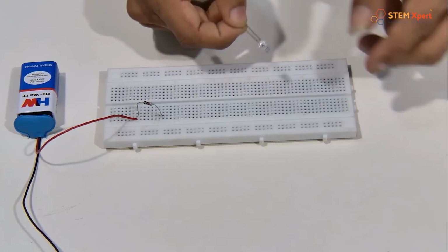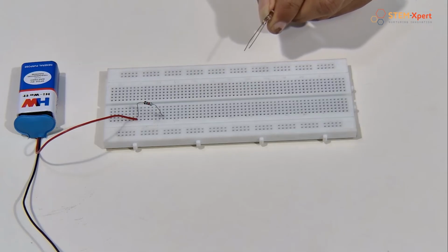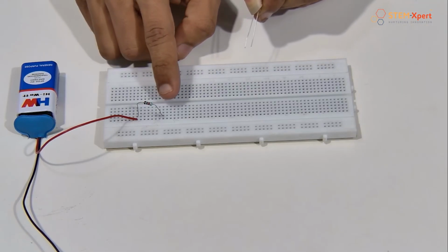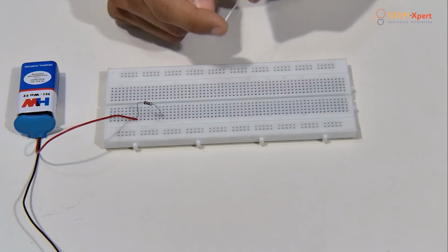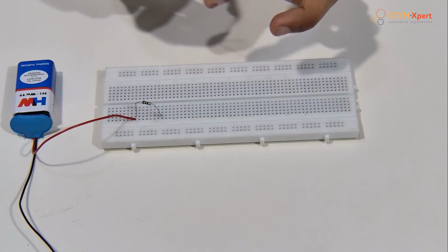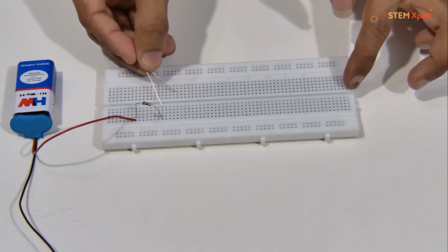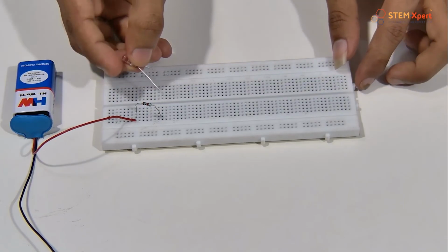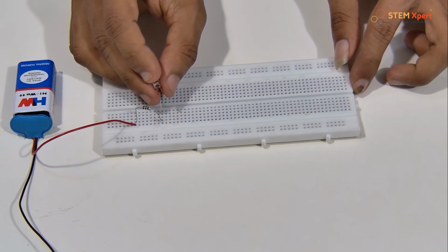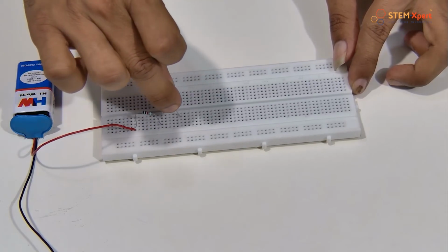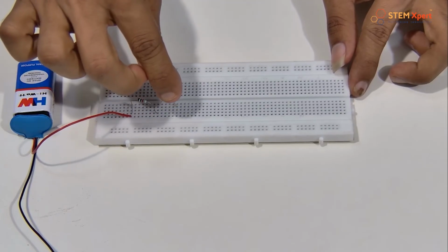You can select a different color of LED from your electronics components kit, no issues with that. So we know that the LED has a positive, the larger one is positive and the smaller one is negative. The thing is that we need to connect the other end of the resistor to the positive of the LED, right? Yes, here I am going to connect the positive to the other terminal of the resistor. That means here is the positive right now, and I am going to connect the positive of the LED to the positive coming from the 9-volt battery through the resistor, and the negative terminal of the LED I just connected to another point of the breadboard.